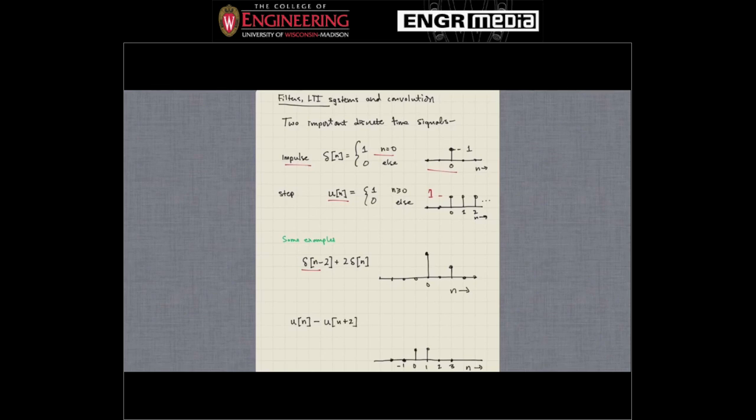So if we think about the signal for a while, we'd see the first thing is that when n equals 0, we're going to get the value 2, because the delta of 0 takes a value of 1, and that gets multiplied by 2. So that's really just this value. And then it's going to be 0 everywhere else except when this first delta turns on.